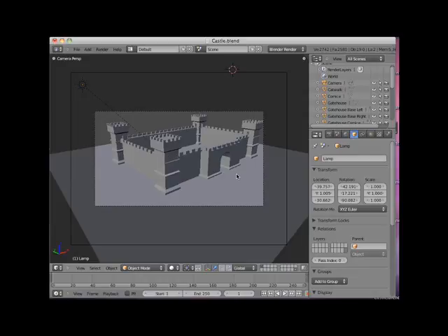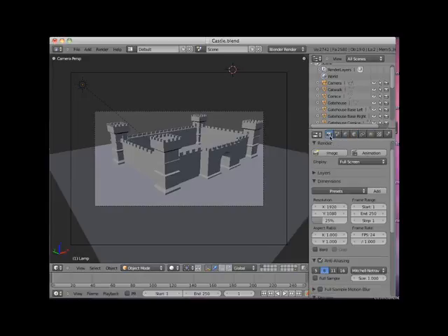The dotted box is really a result of the rendering resolution. If I select the Render Context button in the Properties Editor, we see that the default render resolution is 1920 by 1080 pixels. That's HD TV standard, sized to 25%. This is a letterbox type resolution. If we change the resolution, the dotted box size will also change.